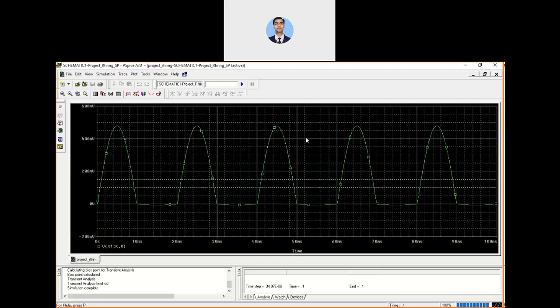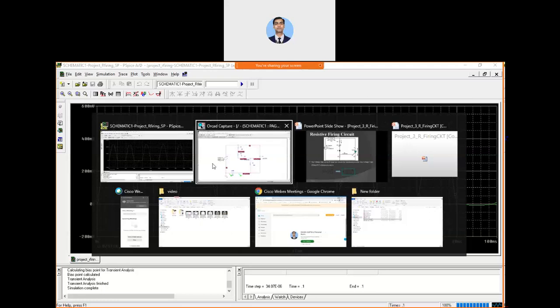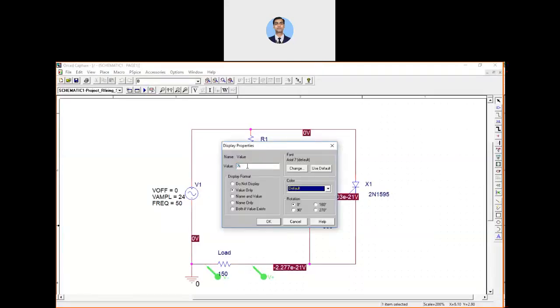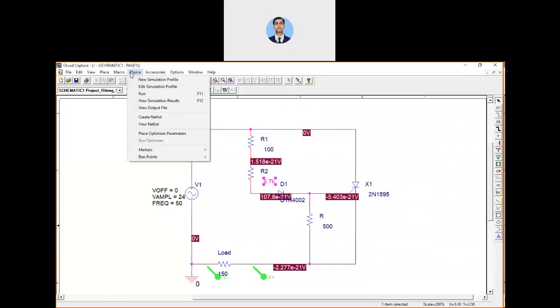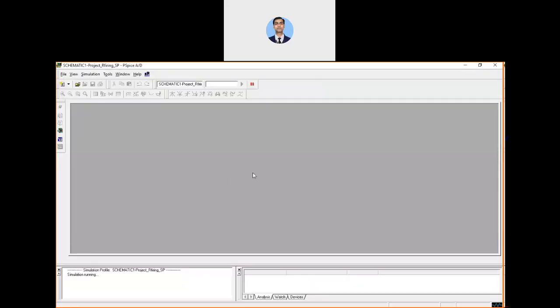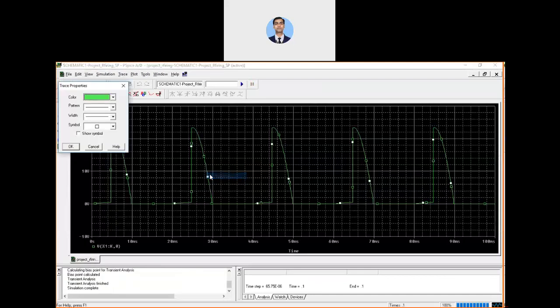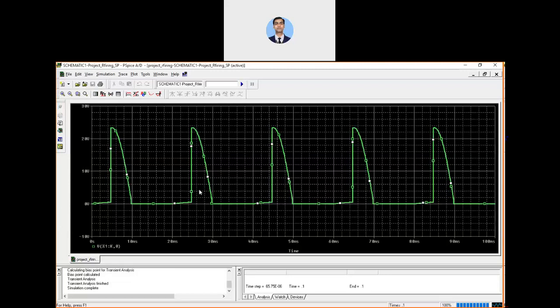You can also refer to your books to understand this particular concept. So I'm going back to the same value for 90 degrees, which I placed earlier, 6.7 kilo ohm. Now run this. So this is your waveform when it is getting triggered around 90 degrees. Now how to measure this?